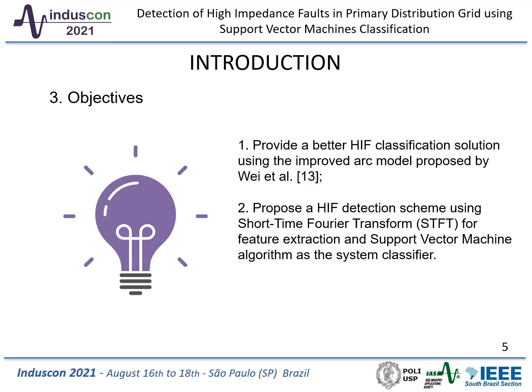So the two major objectives of this work are, number one, to provide a better HIF classification solution using the improved arc model proposed by Wei, and number two, to propose a HIF detection scheme using short-time Fourier transform, STFT, for feature extraction and the support vector machine algorithm as the system classifier.